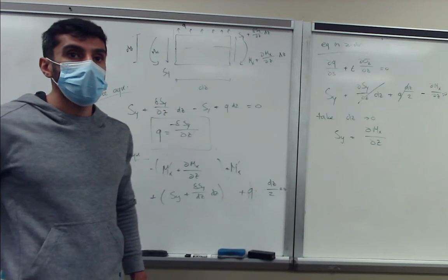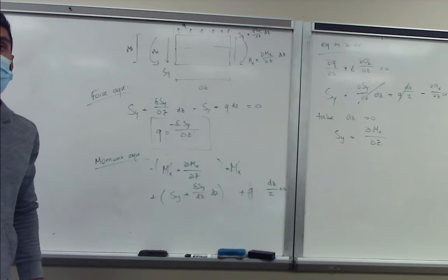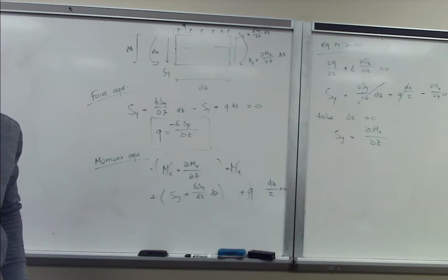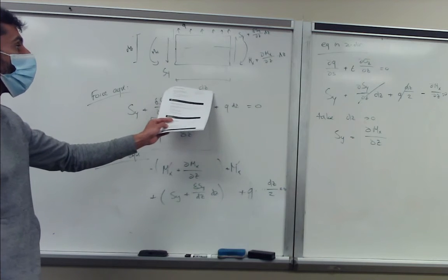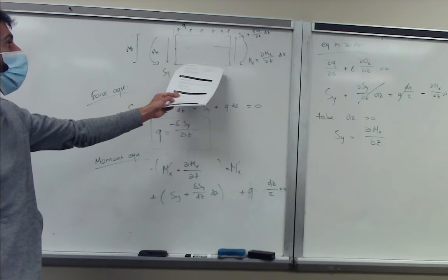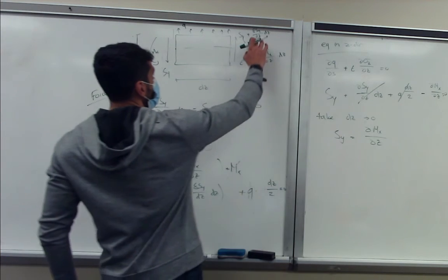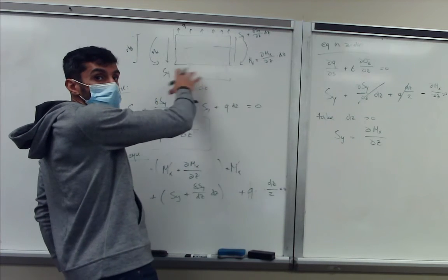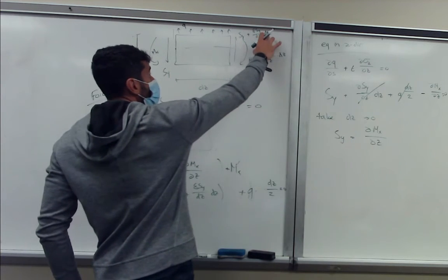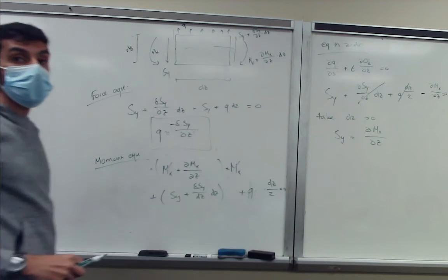So the variation in z doesn't have to go to 0. If the differential element of z goes to 0, the moment arm becomes smaller and smaller. So basically, if this goes to 0, the contribution that you multiply by the length goes to 0. So this drops. But the variation of this function with respect to z doesn't have to go to 0.